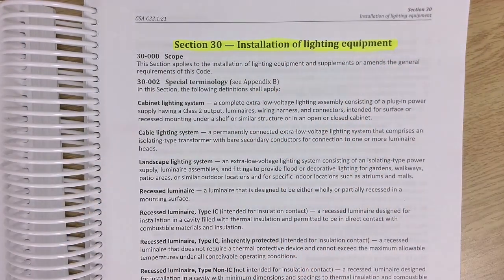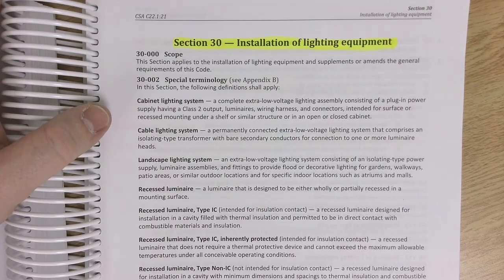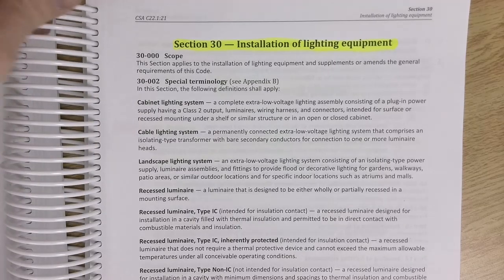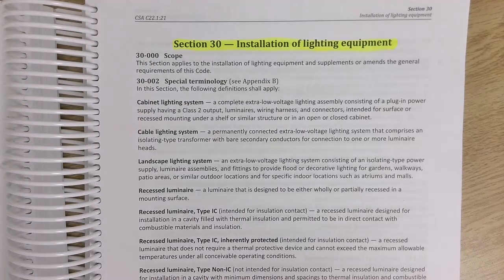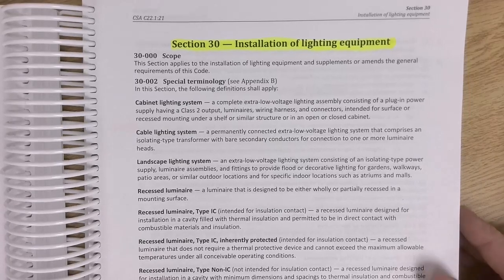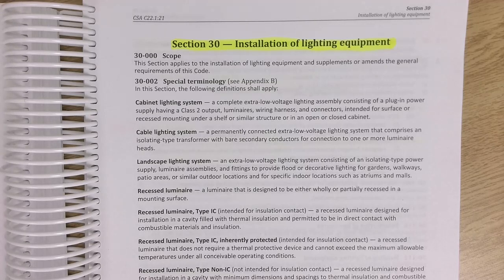Now, if you have installed lights in residential electrical, or you've installed residential lights, I should say, however you want to twist those words, you may already know what type of voltage and amperage those lights are. Normally they're almost always 120 volt, 15 amp, or they're 120 volt rated lights fed from a 15 amp breaker.